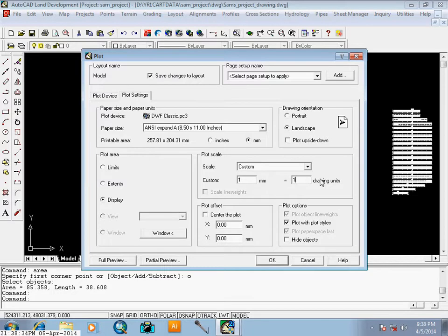I think that is even more convenient. The other side, when we are doing the setting, you should put 1 in 1 instead of 1 in 1000, so that here when you want to print, it's the same. Here I'm putting 1 because the other side I put 1000, but you are told to print this work at a scale of 1 in 1000. So had I put 1 the other side, I would put just 1000 directly here without bothering to calculate. But since I put 1000 the other side, here I put 1.